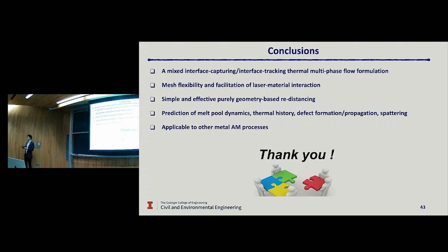And regarding the formation of the bubbles, this is the beauty of the level set method. If there is a bubble, the level set convection should capture it. You don't need to worry that in the beginning you don't have a bubble, but later on you have a bubble. This can be automatically captured by the level set. That's why we still want to have a level set in the formulation. Otherwise, you have to remesh. Yeah, thanks.